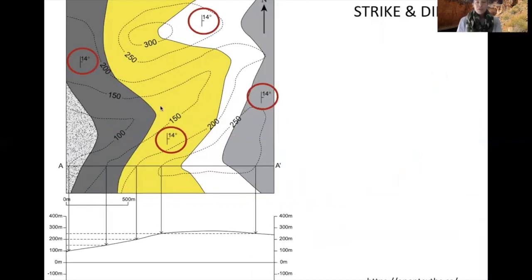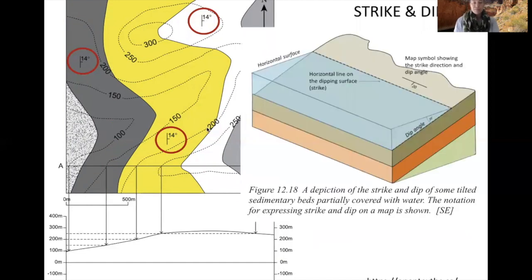So I have a few pieces of information, not very many for dip angle, and I'm going to have to use my best approximation to assume it's pretty similar across that cross-section line. Since my cross-section line doesn't intersect any of those measurements, and these measurements can't be simply projected down because they're at a specific rock where they were measured, we just have to take our best guess. But you'll see that these numbers are all pretty similar to each other, so we have a good starting point.